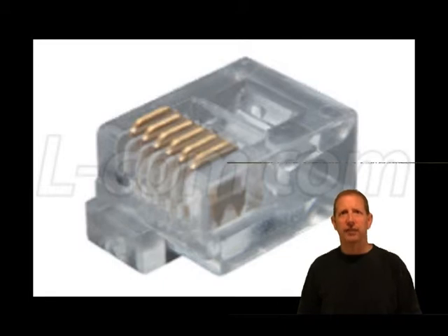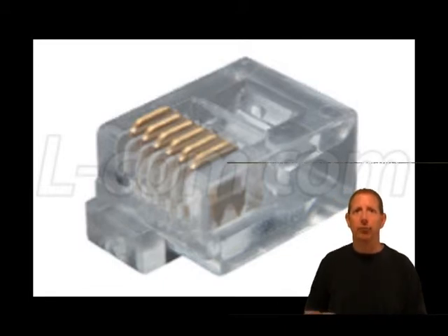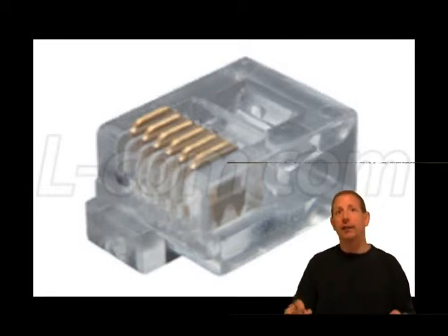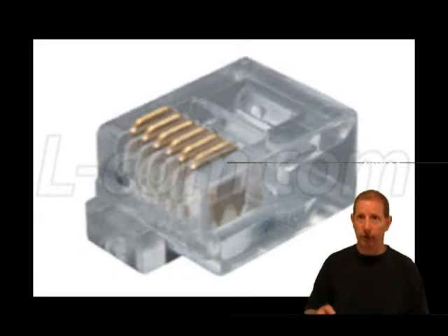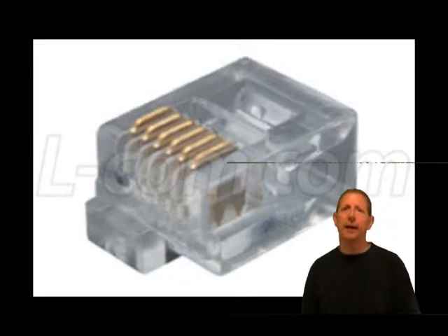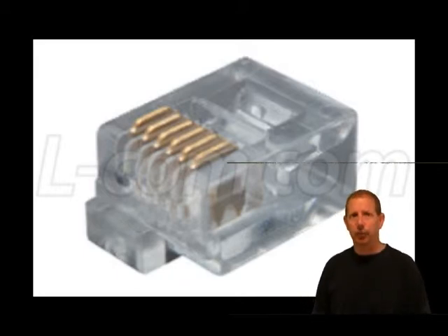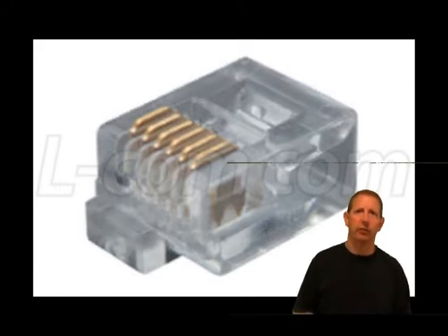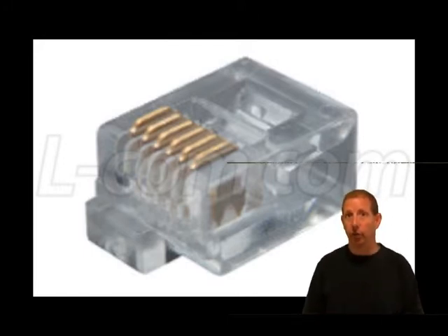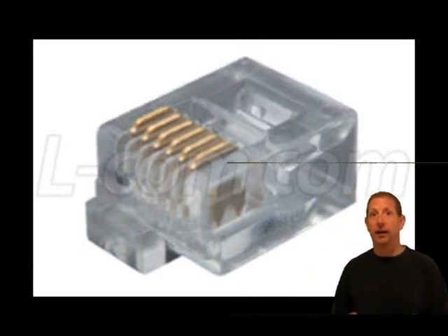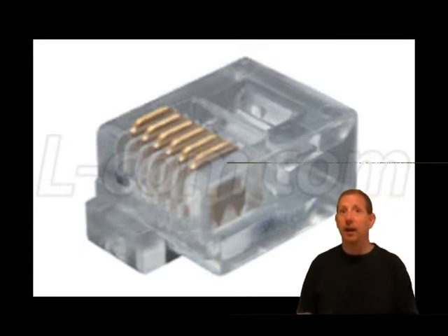An alternate style of key jack is the MMJ style that was used by Digital Equipment Corporation, which we talked about in Chapter 3. This jack has primarily been used for the connection of an RS-232 or RS-422 low-speed devices, and is rarely found in other uses. It is not appropriate for standards compliant LAN wiring.